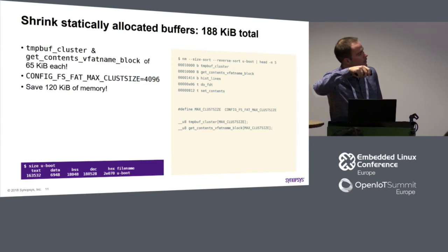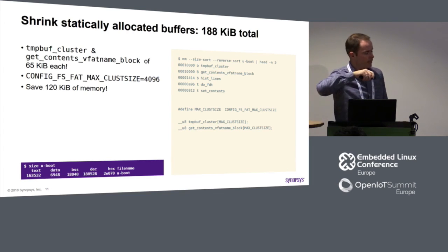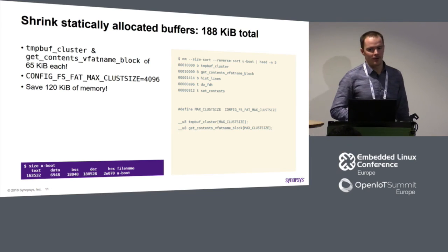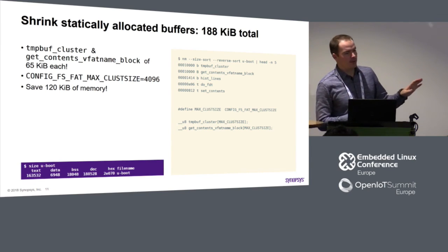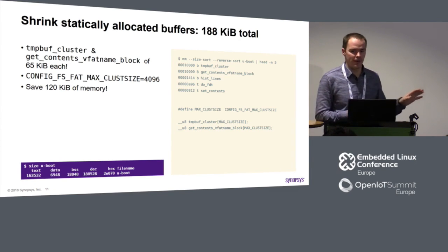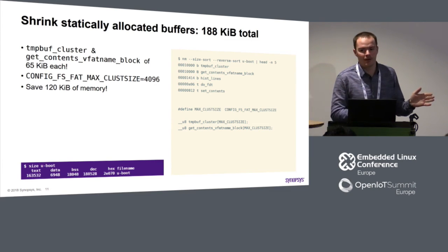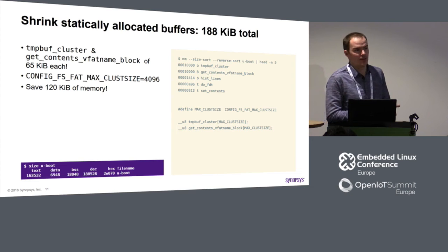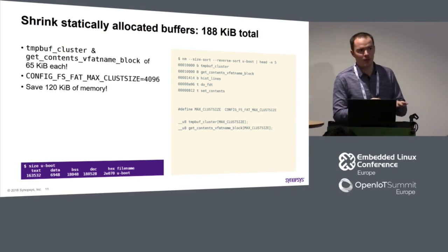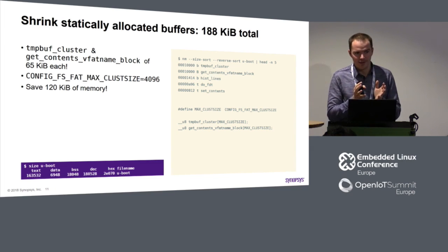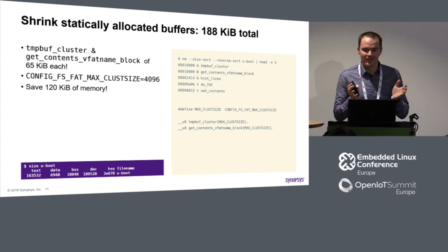If you remove the USB and the file system and so on, how small can you get? Well, I need to try. Again, I had to implement something which supports both SD and USB, and especially USB and the file system add quite a lot. But then the question is, if we remove all the peripherals and leave only U-boot's core, why do we need that? It's just a thought experiment, really. How small can you get?